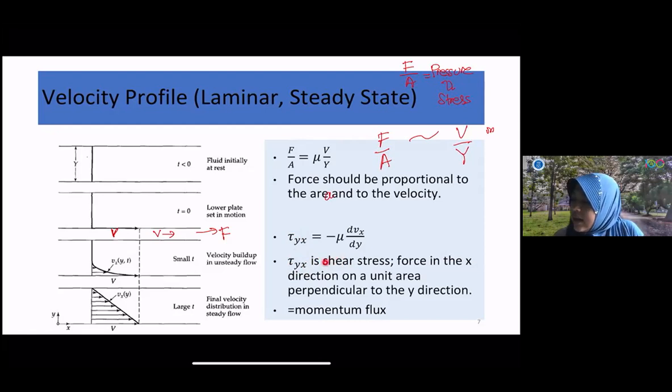Okay, and then the shear stress is the force in the x direction on a unit area perpendicular to the y direction. So tau yx is called a shear stress, which is force in the x direction, because the force is in this direction, and perpendicular to the y direction. Okay, so this is the area, and the area is perpendicular, tegak lurus, to the y direction.